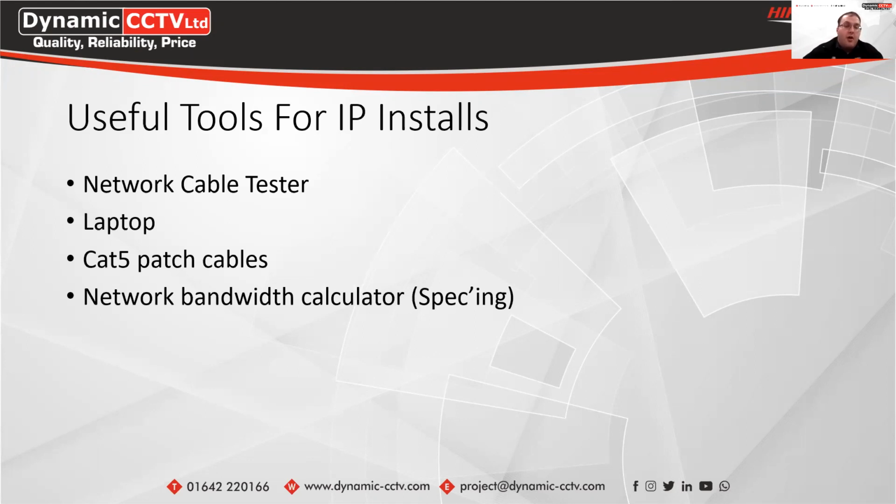And also always carry spare Cat5 patch cables. These are great for testing if you need to take a camera off an existing cable run and just test it locally on the recorder. You can use one of the patch cables instead of having to rerun a cable for quick and easy testing on there.